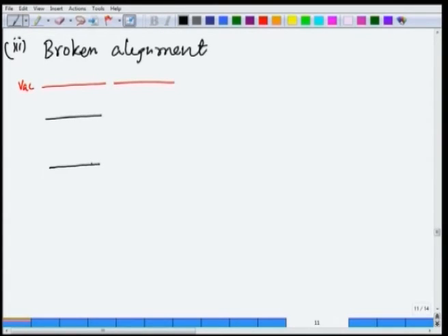this is one semiconductor, and the other semiconductor is actually even below this. So this is EC2, this is EV2, and this is EV1, and this is EC1. And what we are going to do is join them somewhere here. Unfortunately, in this case, the EC2 level is even below the EV1 level, and hence it is being called broken alignment.